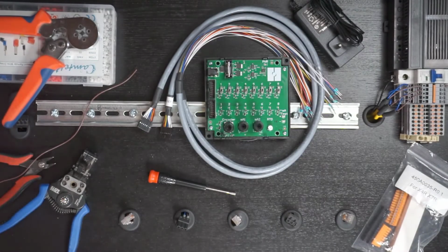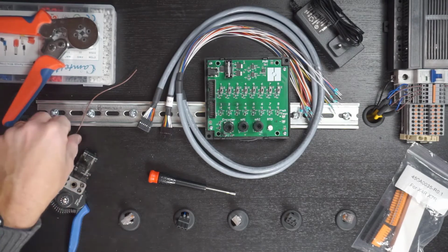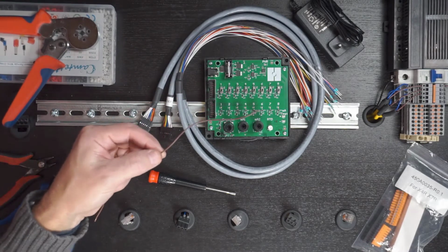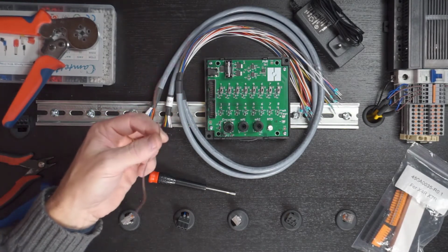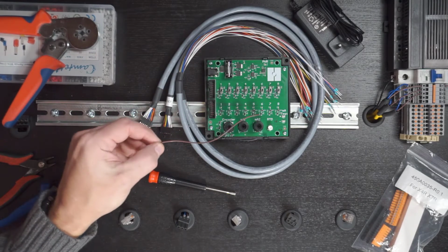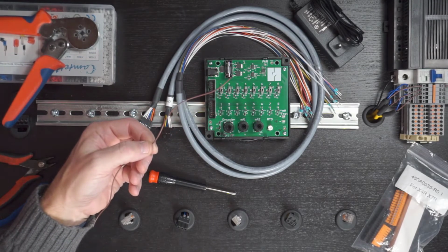However, if you're going to be using, let's say, the relay version, and you need to build up a jumper assembly to jumper the V+ signal to all the relay commons, then I'd suggest you also get maybe a couple feet, this is only about a foot, but maybe a couple feet of small gauge wire. I think this happens to be 20 or 22.